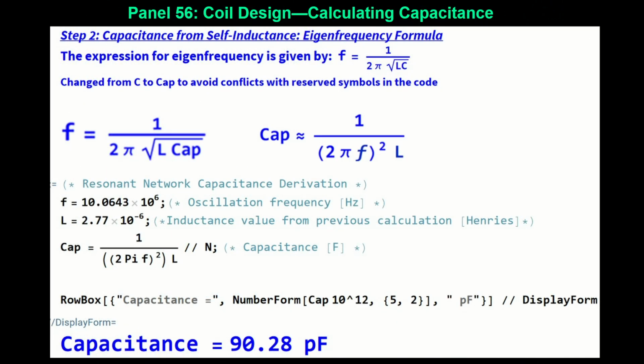With inductance values established, I needed to determine tank circuit capacitance to fine-tune resonance frequency. Since direct access to the oscillator's protected PCB was restricted, I measured capacitance wirelessly using a Yaesu transceiver. By detecting peak resonance frequency and knowing the coil's inductance, I applied standard LC resonance equations to estimate capacitance. Matching capacitance to the coil ensured energy storage efficiency within the tank circuit, reinforcing controlled plasma oscillations while maintaining frequency stability.